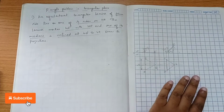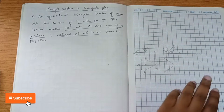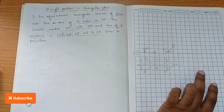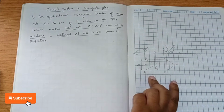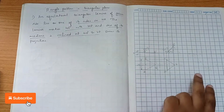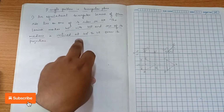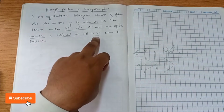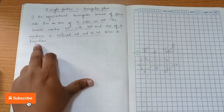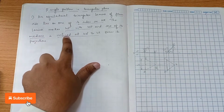Now the only change with respect to a normal type problem and this beta angle problem is in the third position. The first two positions remain the same, that's why I have drawn these two positions initially. Now we have to construct the third position. One of its medians is inclined at 40 degrees to VP. You can see the median is given for an equilateral triangle, so it is a beta angle problem.